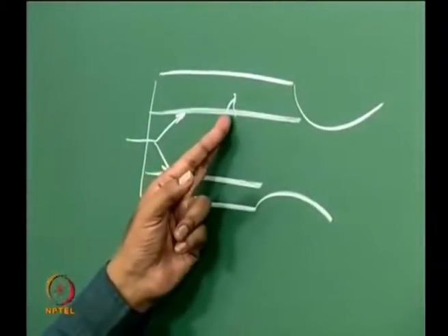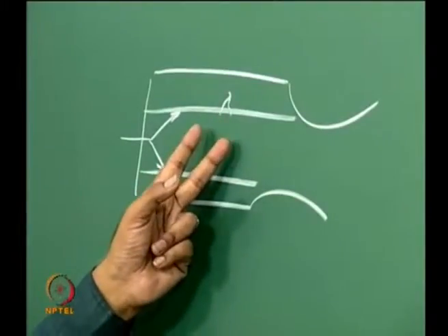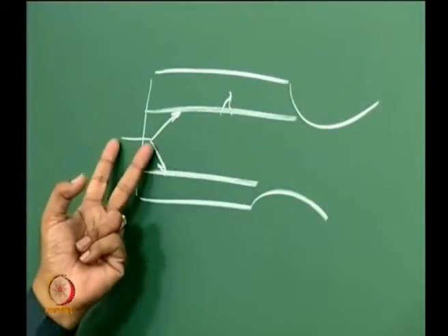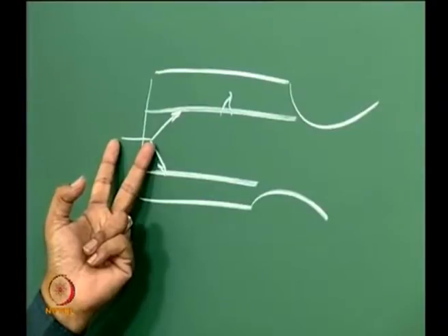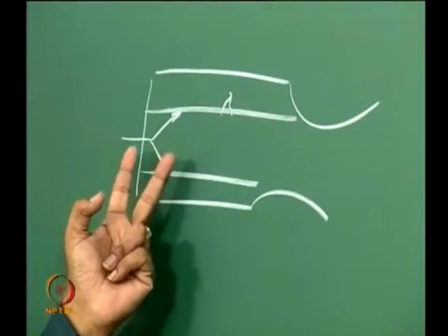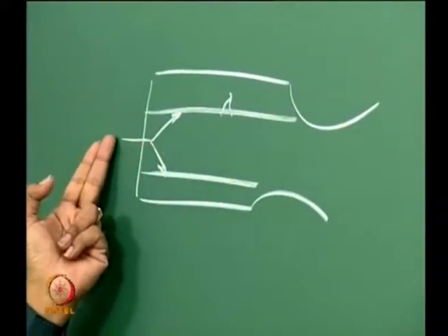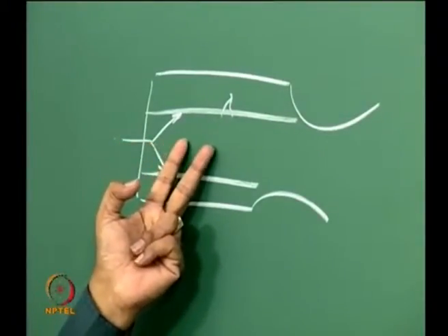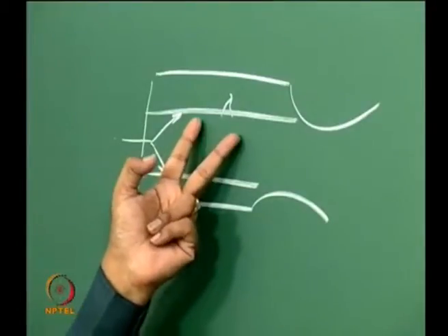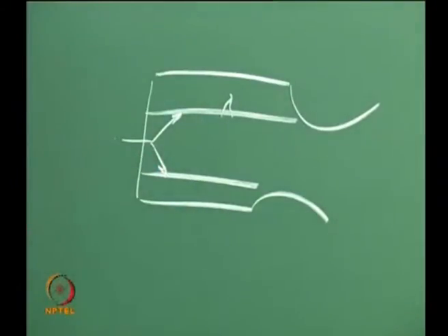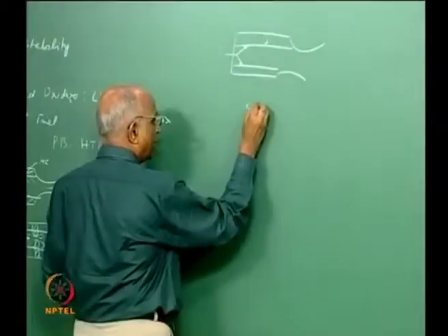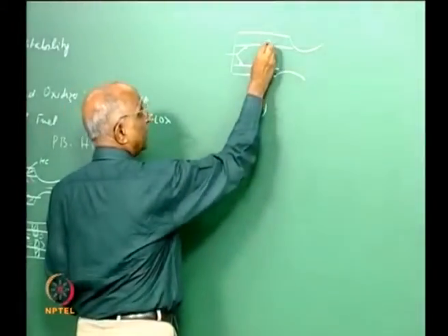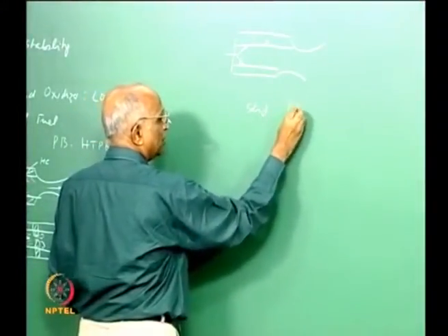Because the surface area is increasing, the pressure gets generated. When pressure gets generated, automatically the pressure drop across the injector decreases, because the pressure here is higher and this is constant pressure. The pressure drop gets decreased, and therefore the flow rate of oxidizer decreases, and therefore it is self-regulating. In other words, in solid propellant rockets, if there is a crack, its surface area increases and pressure continues to increase.